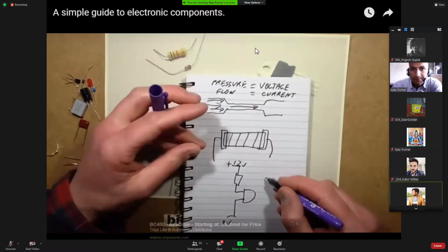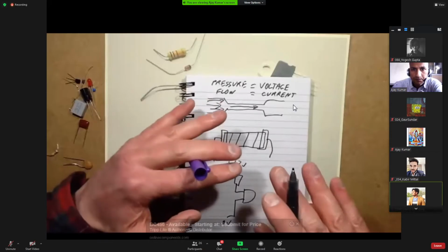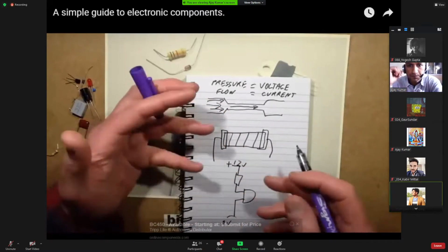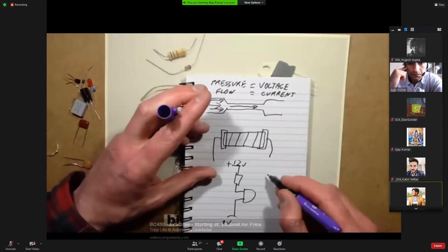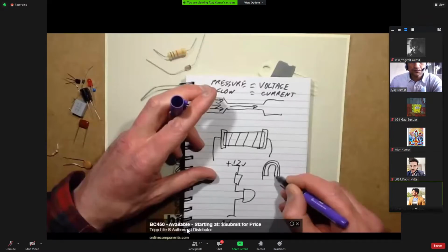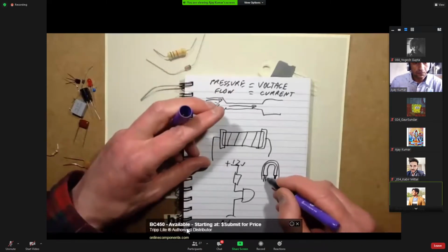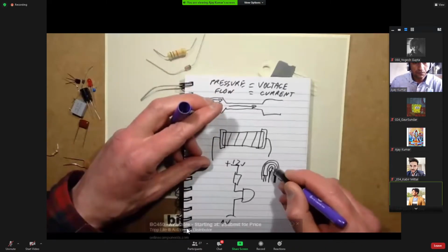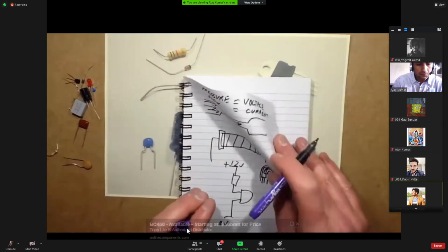You might have a resistor charging up a capacitor. It trickles the current into it until the voltage reaches a certain level, and then that could be used as a timing function. And you also get variable resistors, where effectively it's a carbon track connected at both ends. You only really need to use it connected at one end, with a wiper that wipes round that track so that, depending on its position, that will vary the resistance.